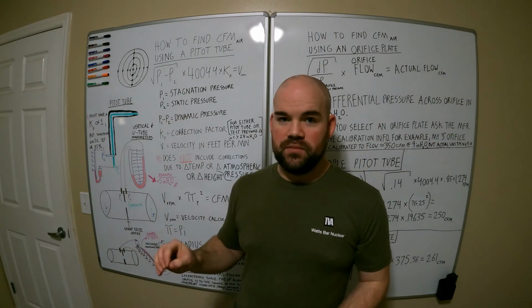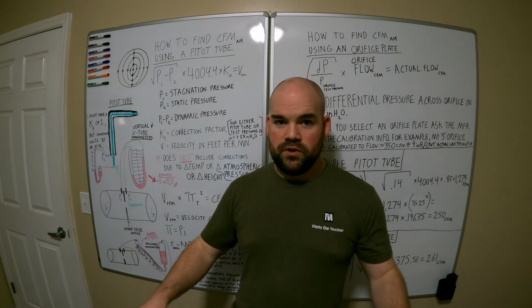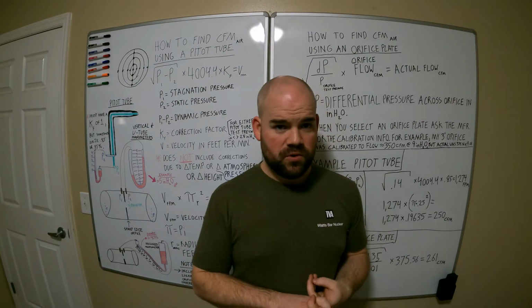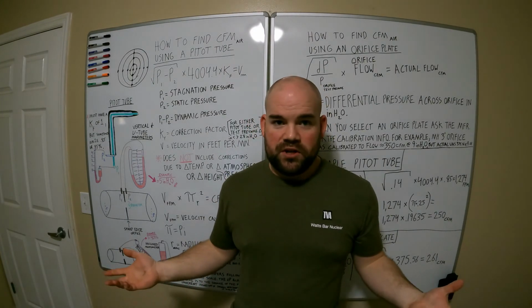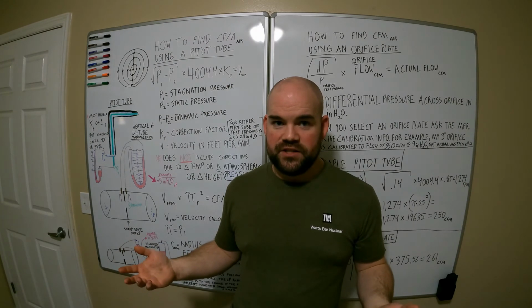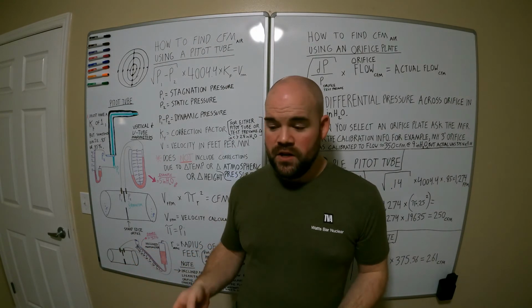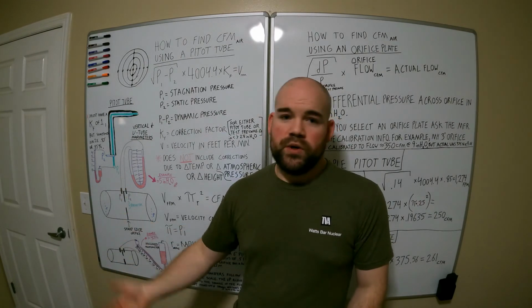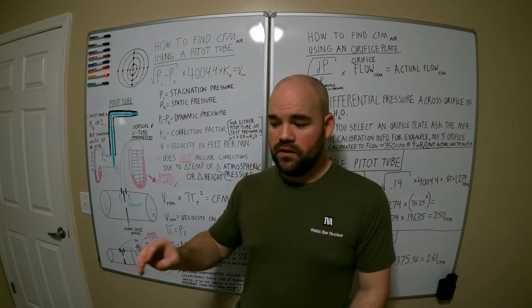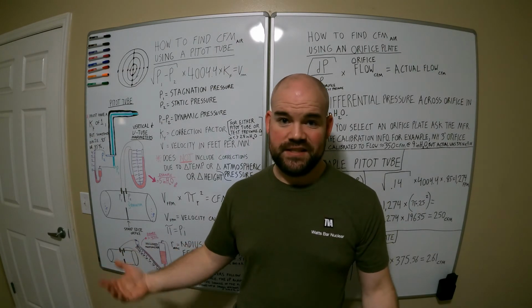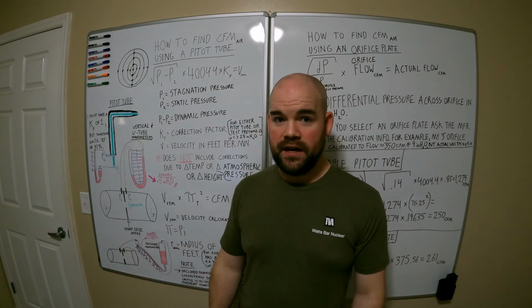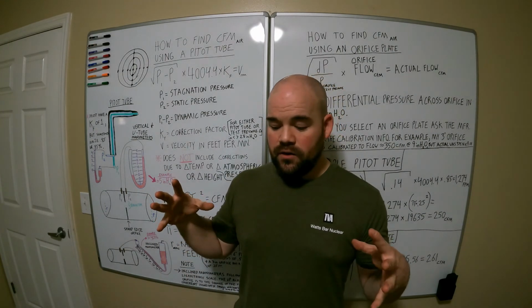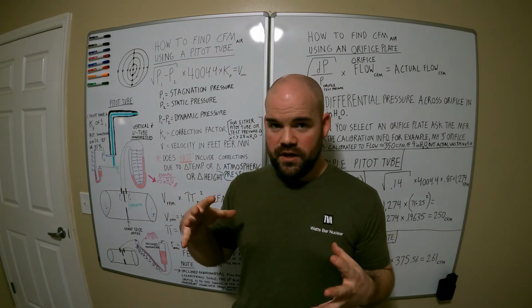It's because of the temperature, okay? Boost is no different. If you have 1 pound of boost on a supercharged application and 1 pound of boost on a turbo application, it's the same amount of pressure. The difference is temperature, and that changes the density of the air, which is how much power you make. 1 pound of boost on a car that has a turbo could add 20-ish horsepower. On the roots style, 6 to 10 horsepower, depending on how much temperature rise. So it's how much oxygen you can cram into that 1 CFM.